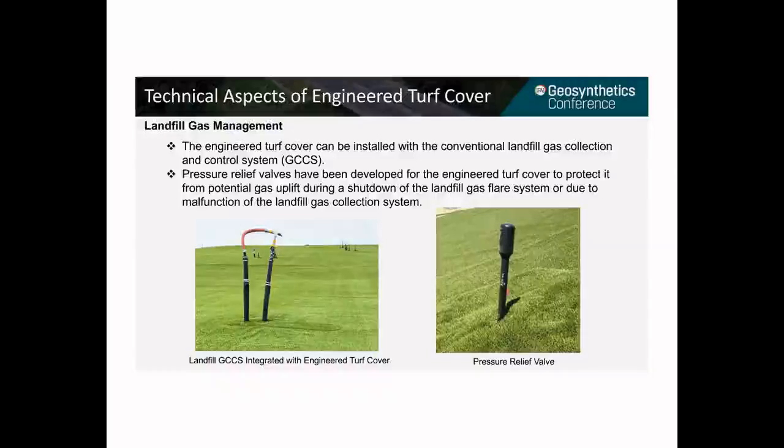Pressure relief valves have been developed for the engineered turf cover to protect it from potential gas uplift during a shutdown of the landfill gas flare system or due to a malfunction of the landfill gas collection system. The figure on the right shows a pressure relief valve installed in the field with the engineered turf cover.